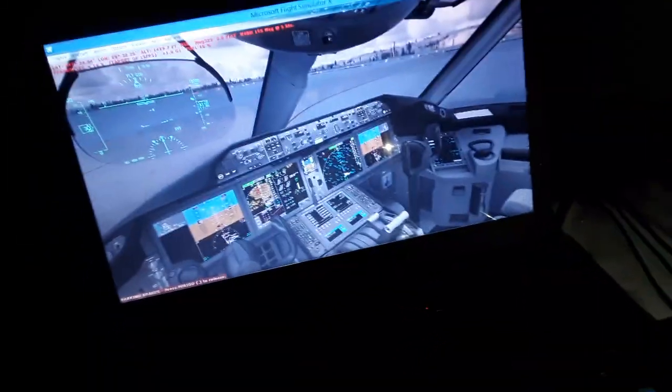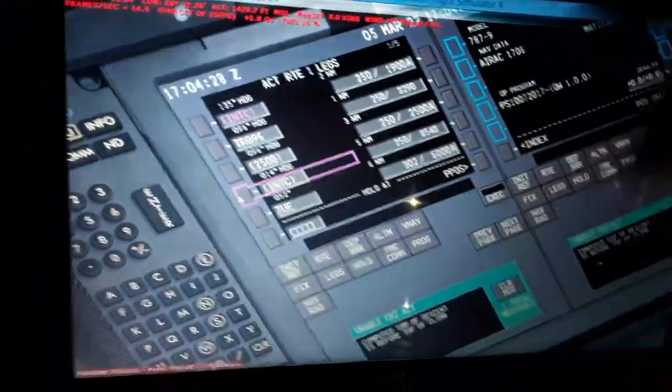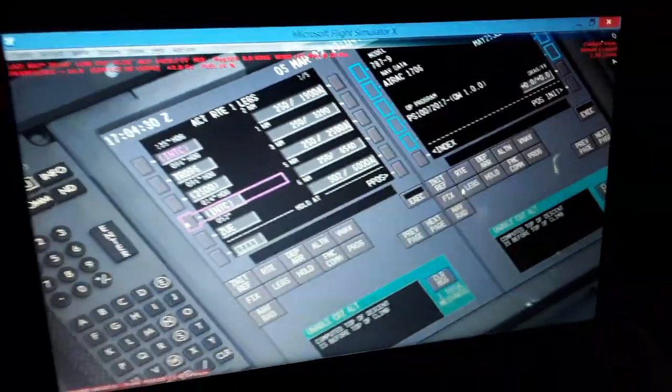Autopilot, flight director system panel, head-up display, the display of the engines, the ACAS, the flight management computer over here. You can see I input all the data I told you about flight. So I input the aerodynamic core position, calculated using the takeoff gross weight, the passenger cargo and the fuel on board. The center of gravity, the trim for the horizontal tail is calculated from this computer, the flight